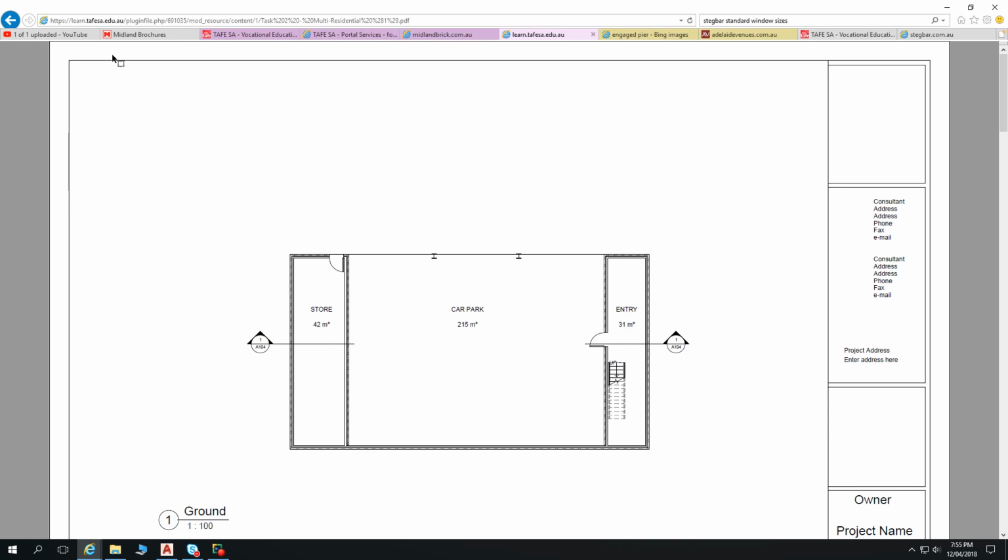But you can say by using this timber beam floor, we can't achieve that required span of 13 metres, and it requires the introduction of intermediate columns. And that's probably good to say 2 rows of intermediate columns, or let the client know how many intermediate columns, because that will really dictate how restricted the use of that car park is. So I guess try to get those details in there.